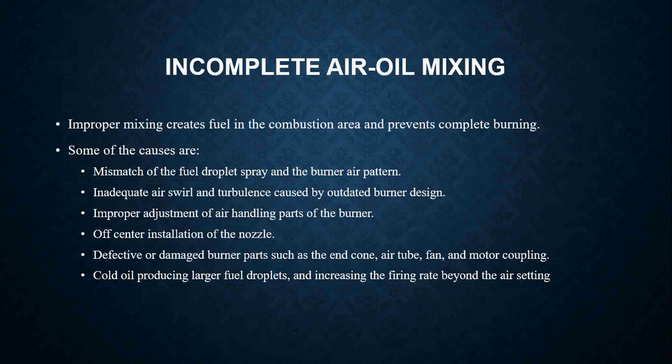Off-center installation of the nozzle. Your nozzle line may be cocked or bent for some reason, or overheated. Defective or damaged burner parts such as the end cone, air tube, fan, or your motor coupling. Cold oil produces larger fuel droplets. It increases the firing rate beyond those air settings.